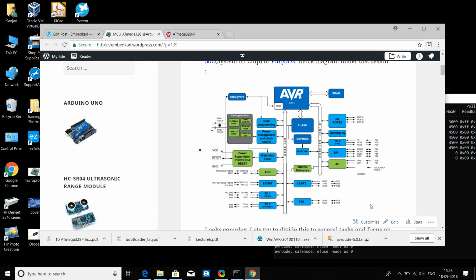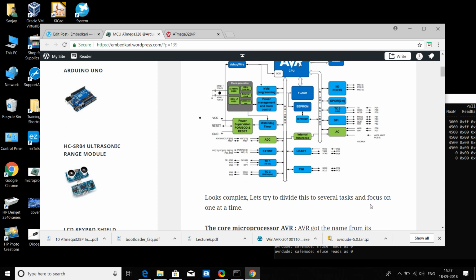And one thing for this particular microcontroller is that this was one of the microcontrollers designed with inbuilt flash. Earlier, there were devices which were using EEPROM, OTP, one-time programmable devices. Once you program it once, it will be useless for you. So that is basically for factory-based use, or electrically erasable EEPROM, or maybe some EPROM where we use ultraviolet rays to erase it. So this was the one.